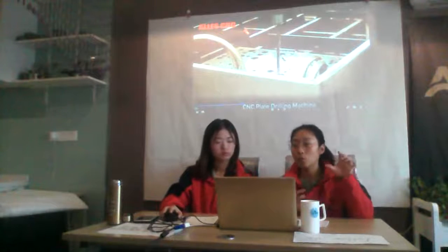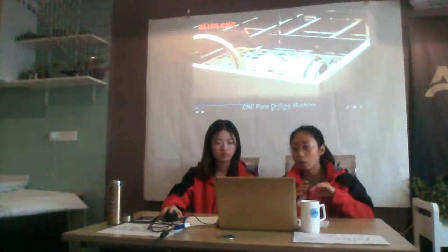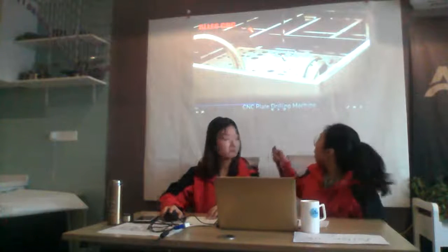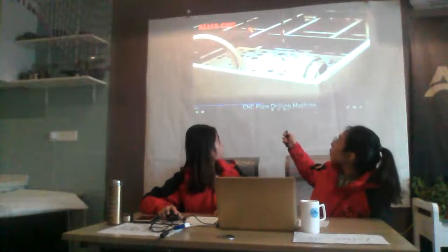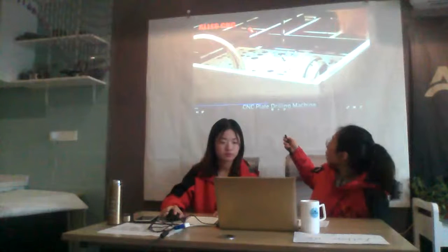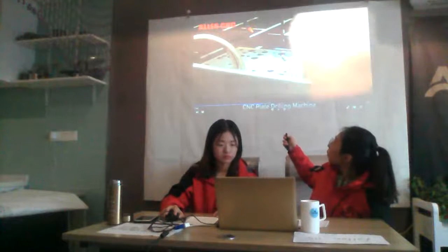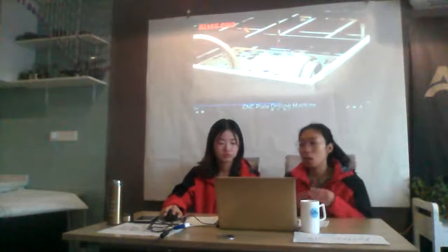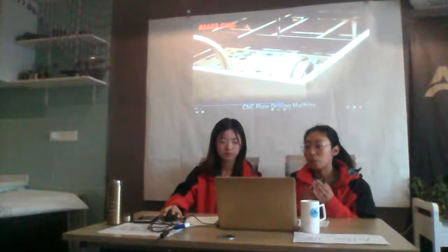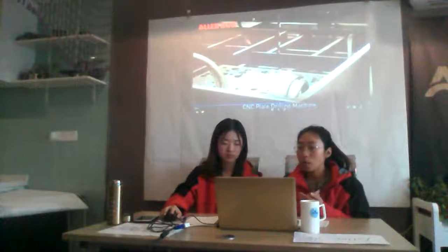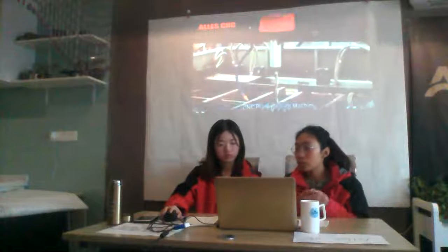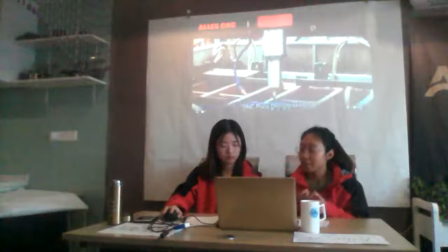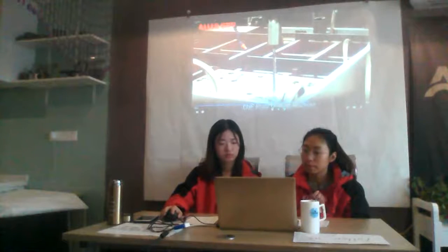And if you want to know the workpiece details, in the video our customer can see very clearly the tools have some burrs, so the processing is not very smooth for this machine because the spindle speed is not very high. So it can't achieve very smooth processing.